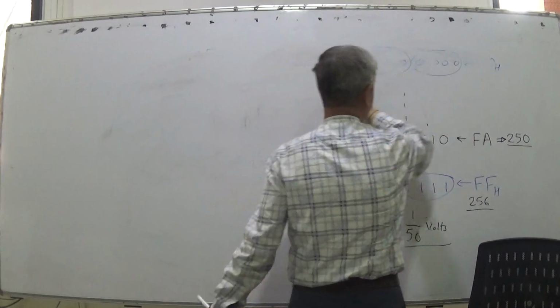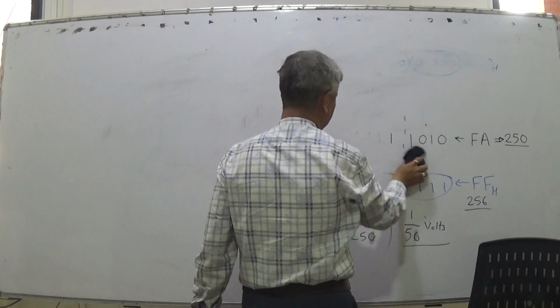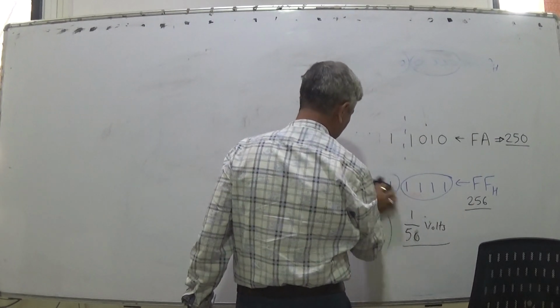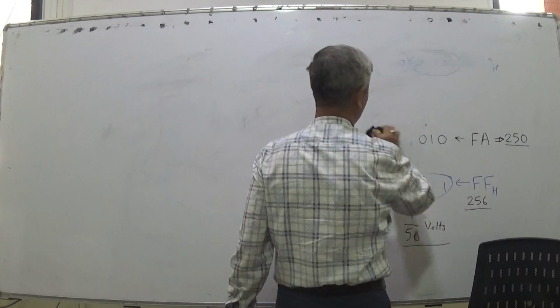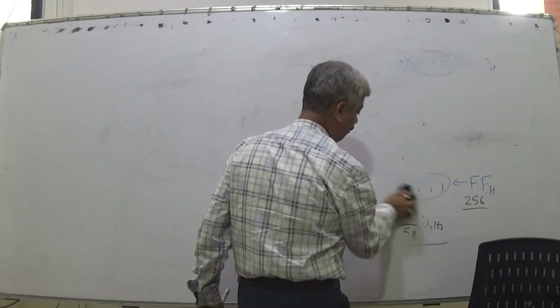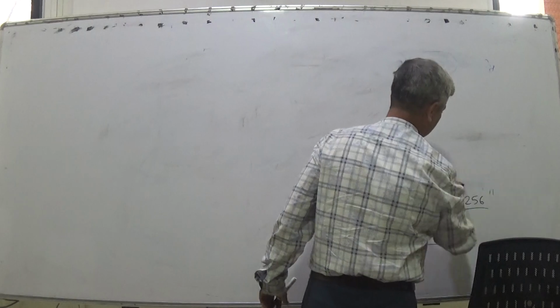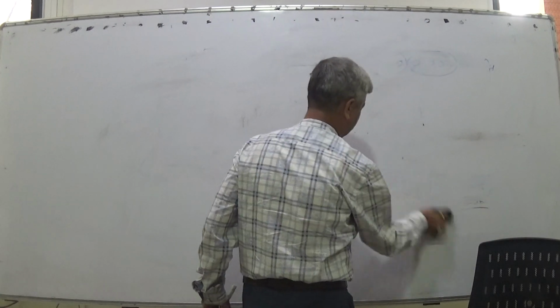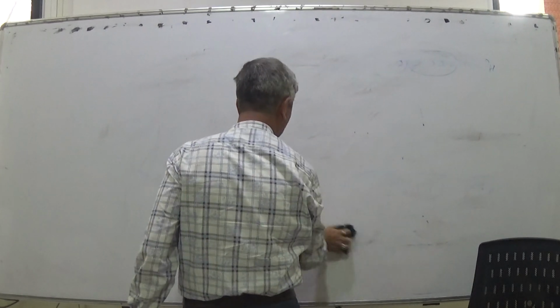The instruction set is wider, a very rich instruction set. When you read that analog input pin, whatever you get is a 10-bit value. In case of Arduino, you get a 10-bit value between 000 hex to 3FF hex, corresponding to 5 volts. That value you take and you can process.